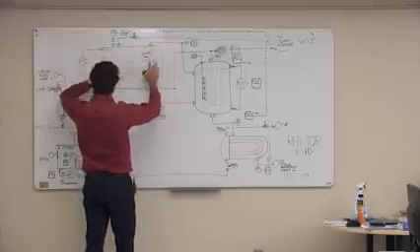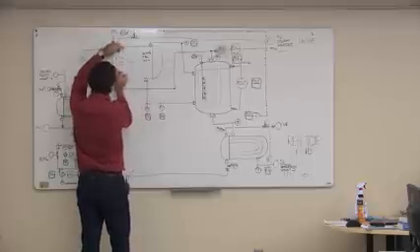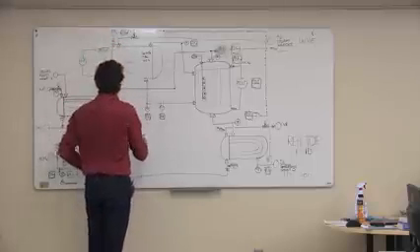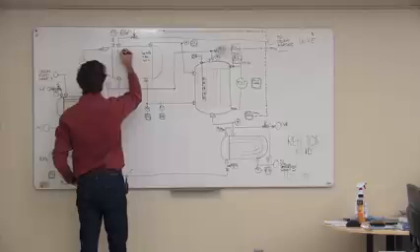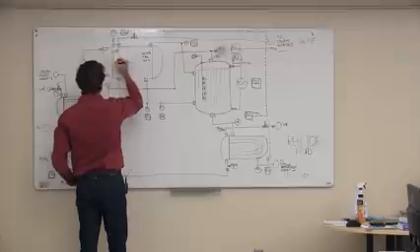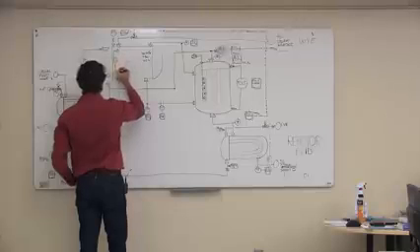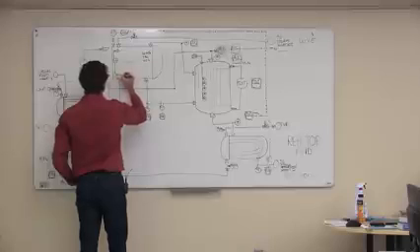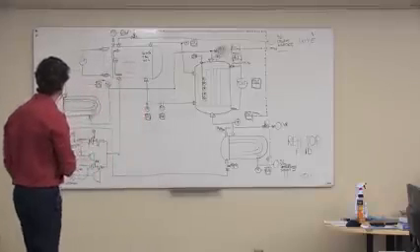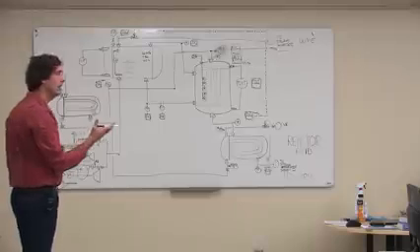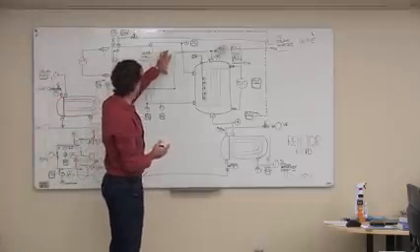Sometimes people, if they're really cramped for space, will draw the sight glass right on the vessel. It's a little bit confusing for some people, but I'm going to do it just to illustrate how that would be shown. So we'd show the nozzle like that. We'd show a valve like that. And a sight glass is an LG. So we do that, come down here like that, and just drop like that. So you can see that it looks like a nozzle on the side of the vessel. I could have just as easily put it here because I've got lots of space there.